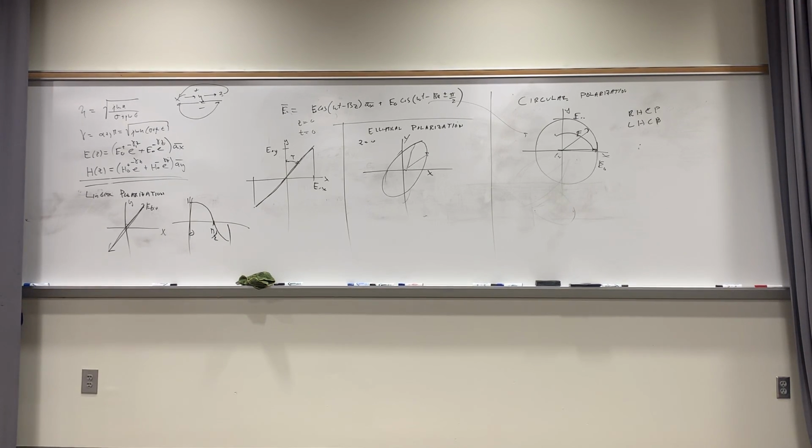Because if I send out a circularly polarized wave with a certain frequency, and I know it's right hand, I know when it hits things, it's going to reflect back at the same frequency, but it will reflect back a left hand. And I can design a filter that will filter out anything but left-hand circularly polarized waves at about that frequency. And then I can get rid of a whole lot of interference, and that's the advantage of circular polarization. Doppler weather radars you've heard of, they use this.